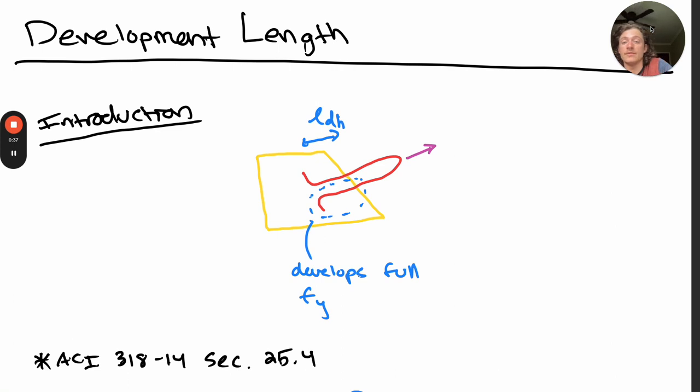Another good example of development length is this. When we check our erection hook tensile capacity, we are assuming that the full 40 ksi strength of the steel bar is able to resist the forces imparted by the winch when hoisting the cables. The erection hook then transfers this force to the anchor, which we check for sliding and uplift to ensure it won't move during hoisting. Great.